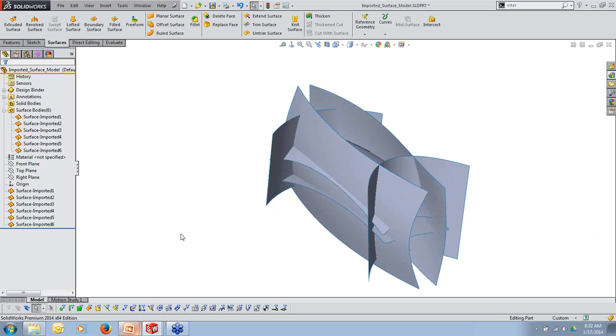If you're not aware of what surfacing is in SolidWorks, surfacing is basically allowing you to speak the language of SolidWorks. It's allowing you to create each face independently, which is what SolidWorks does for you in the background when you're creating solids. It creates all those surfaces and says, okay, I know these are all one unit. Well, when you're doing surfacing, it gives you the freedom to diverge from that. You can create everything independently and then pull it all back together.